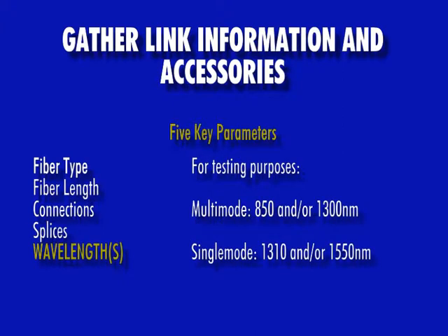Lastly, the user must determine what wavelengths they will test at. For multi-mode, this is 850 and or 1300 nanometers, and for single mode, this is 1310 and or 1550 nanometers.